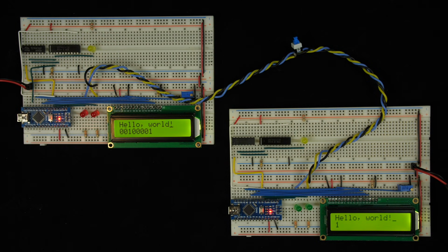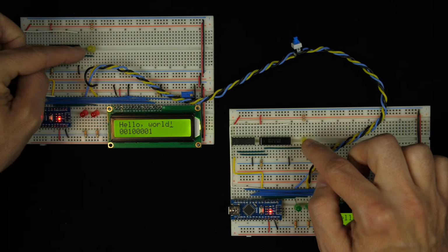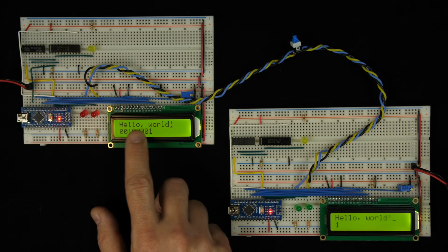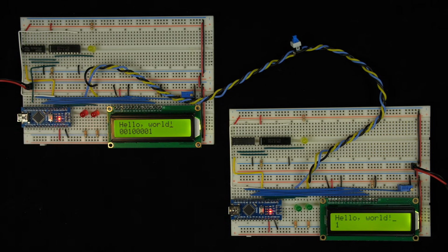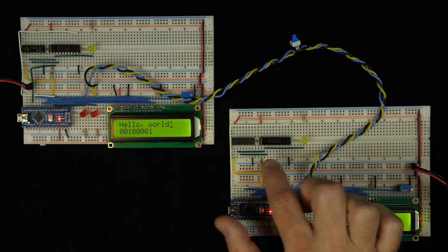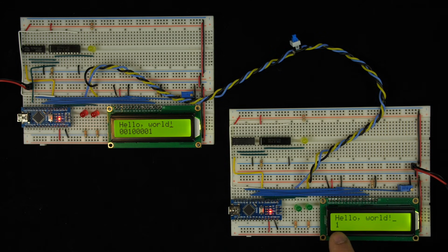Okay, now it's done. And you'll notice right away that both of the parity LEDs on both sides are off. So that suggests that we must have sent an even number of 1 bits and received an even number of 1 bits. And of course, our message hasn't changed. It still has an odd number of 1 bits. But now we've also sent the parity bit, which remember was a 1. And that's actually this 1 here that you can see on our receiver. But of course, our parity computing circuit is very simplistic. It doesn't know the difference between the data bits and this parity bit.